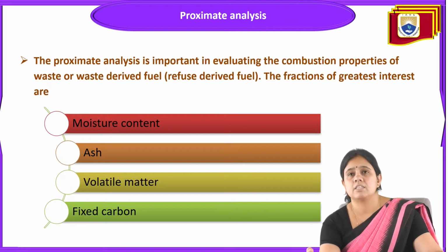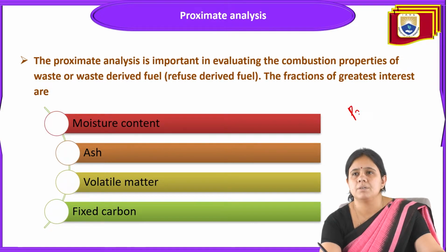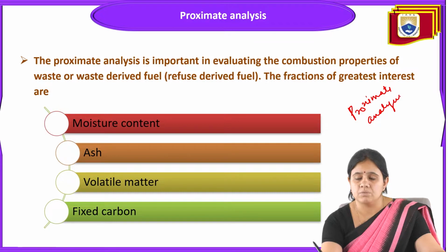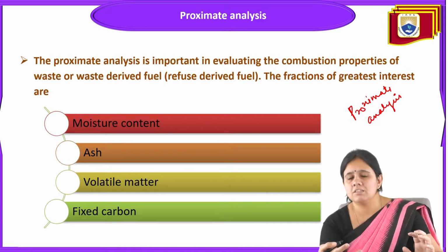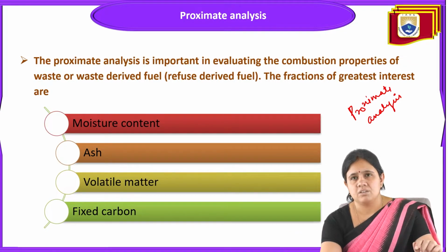Now comes the next point, proximate analysis. Proximate analysis is a very important term regarding the characteristics of the waste. This analysis is important in evaluating the combustion properties of waste or waste derived fuel. In proximate analysis we evaluate the properties of waste, like how much fuel we can derive from this waste, refuse derived fuel, and how important this waste is for getting the heating value.